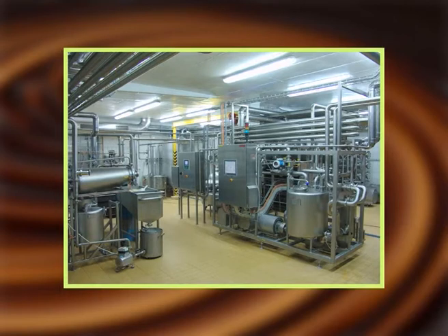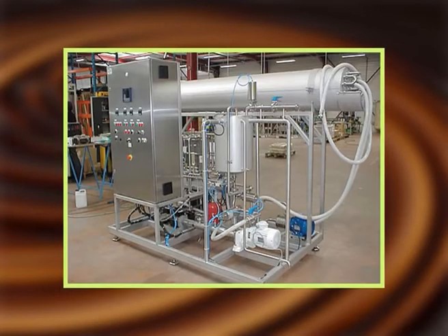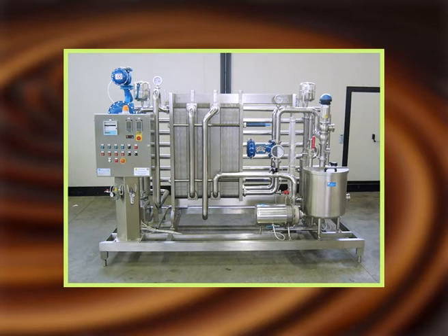Homogenization of the mix should take place at the pasteurizing temperature. The high temperature produces more efficient breaking up of the fat globules at any given pressure and also reduces fat clumping and the tendency to form heavy-bodied mixes. The higher the fat and SNF in the mix, the lower the pressure should be.